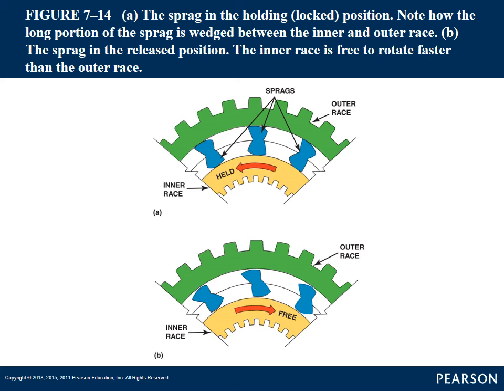So if you're driving a truck, and you usually get this in lower gears, say you're in second gear trying to pull a load and you're getting it up to a higher RPM and you let off the gas, that allows that transmission to freewheel and kind of eases up on the wear in the transmission, and it almost goes into like a neutral position. But as soon as you apply driving force back to it, it would turn the races in the different direction and would lock the sprag in place or lock the roller clutch in place.